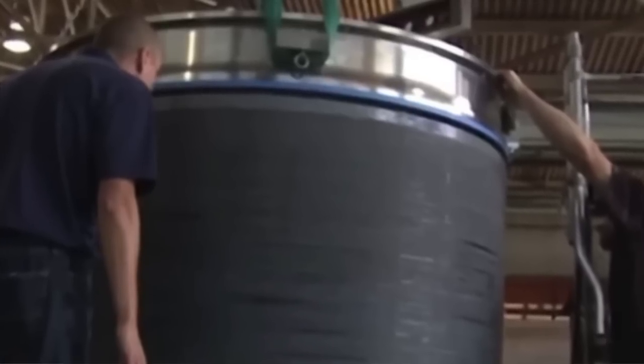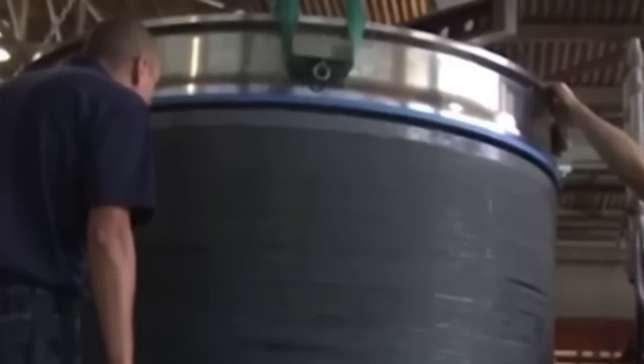The final concern is over the bond joint between the titanium end caps and the composite center section. As you can see in these pictures, the end of the composite tube is machined down to mate in a groove in the titanium end sections. Well, how do you join titanium to composites? It's not like I have a piece of steel and another piece of steel and I'm welding them together. Well, the answer is that you just simply glue them together. And here you can see them mixing adhesive and applying adhesive by hand.